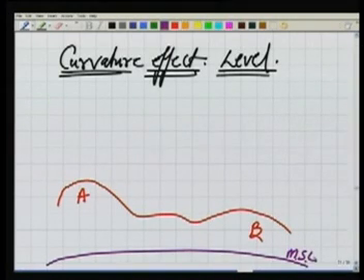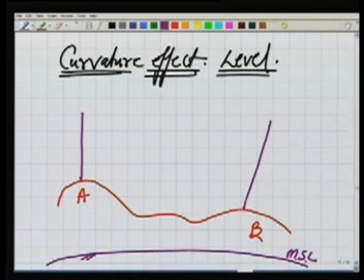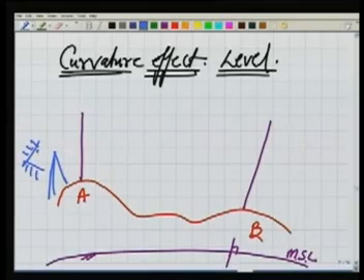So ideally, in order to determine the difference between these 2 points A and B, I should establish a surface which is parallel to the mean sea level. But what we do, because we are making use of level and staff combination, I keep a staff here and I keep a staff here. A staff is kept in both the places in the direction of the gravity, vertical. So that's why I am showing it like this, because this is perpendicular here. Okay. Now I keep my level somewhere here, and that's the eye. From here I am looking at.